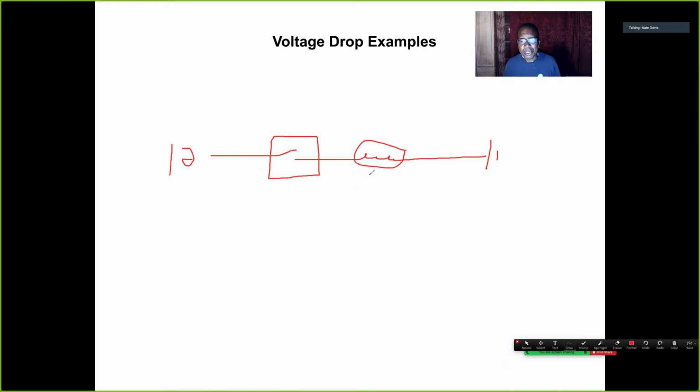And obviously on a good circuit, when this circuit is energized and these points are closed, this circuit should drop 12 volts. And the light comes on and it's bright. Now, like I said, I'm using a light bulb. This could be a fuel pump. This is going to be a coil. I'm just using a light bulb because it's easier. All right, and that's a normal circuit.